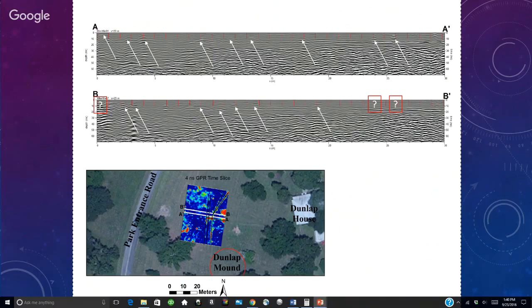And they were able to identify a number of utilities in this area that were buried, many of these not being metal and could not have been detected with traditional EM locating equipment. So ones that do not hold a current could not have been detected with that. But in this case, we were able to get a three-dimensional view of what's below the surface here. We found a number of buried utilities, whether they're water pipes or power or what have you.